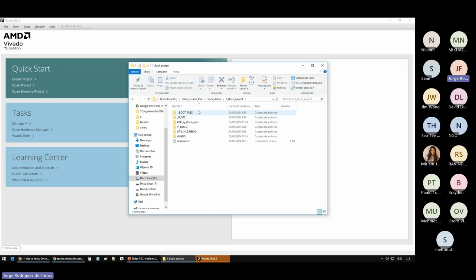It has the high-level synthesis IPs, which are the gain and offset adjusting, some format converter, the moving average filter, PID compensator, digital PWM modulator, etc. We have in here the Vivado project, and in here it is the project for the microprocessors.